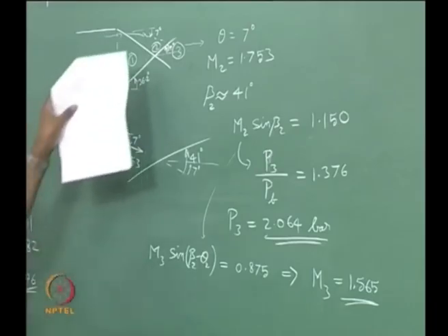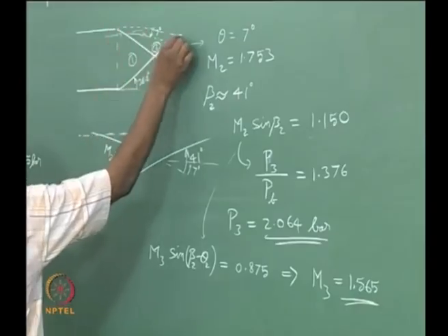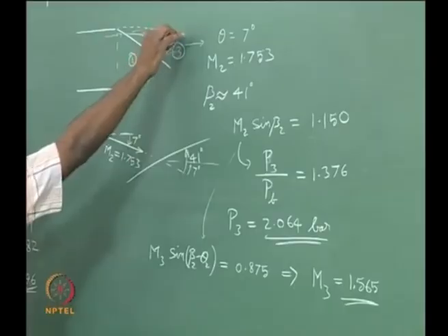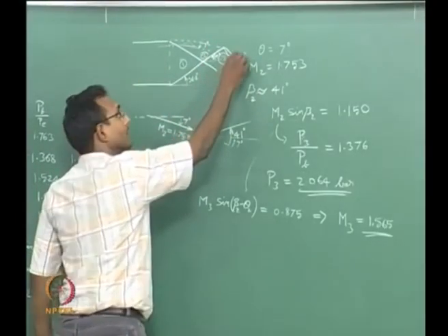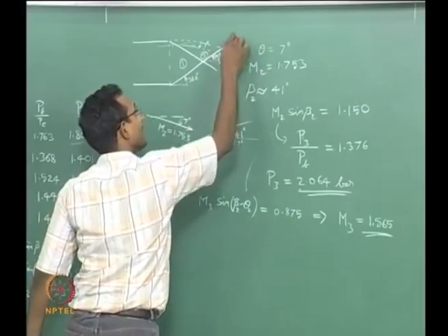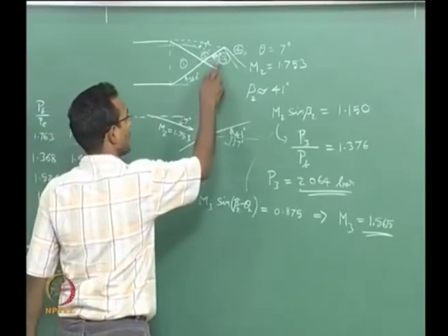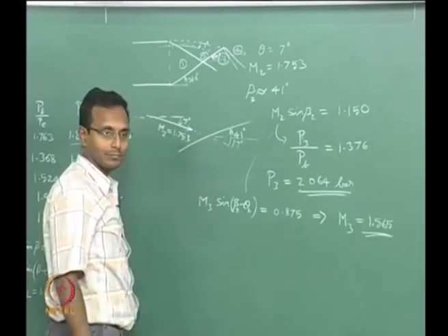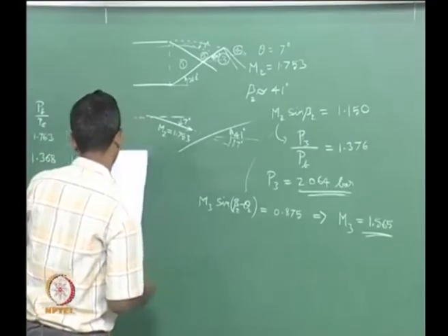Now we want to continue the calculation even past this point. Now I know my dotted line, if I extend for my jet boundary, when the shock reaches there, after that there has to be some expansion fan here such that the pressure in this region 4 is same as my back pressure, the outside pressure. So from 3 to 4 I need to have expansion fan. Okay, simple calculation after that. We know expansion fans are easier to calculate.